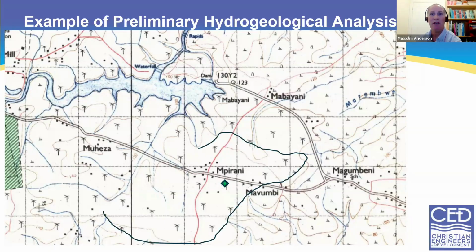And that is what that line is. That's the 120-meter groundwater level contour, just drawn straight off the topographic map. And similarly, you'll notice that these two streams here start here and here at a higher level. That's 120 meters there and there, but they go some distance further. So they're around about 130. So I can put in a notional top to this system of 130.